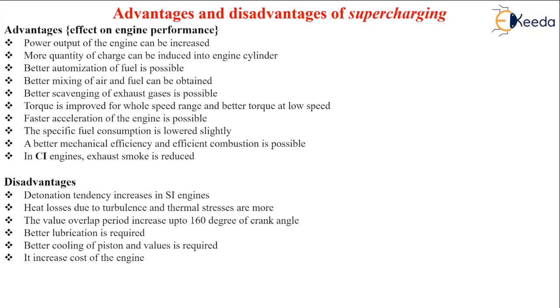Then again, as the power output increases, the torque will be improved for the total speed range of the engine, and also at lower engine speeds it will give you a better torque. Then again, acceleration of the engine is vastly improved because the air fuel mixture becomes more homogeneous, and since it is compressed, it will burn at a higher rate and thereby release a greater rate of pressure release and heat. Hence acceleration will be better.